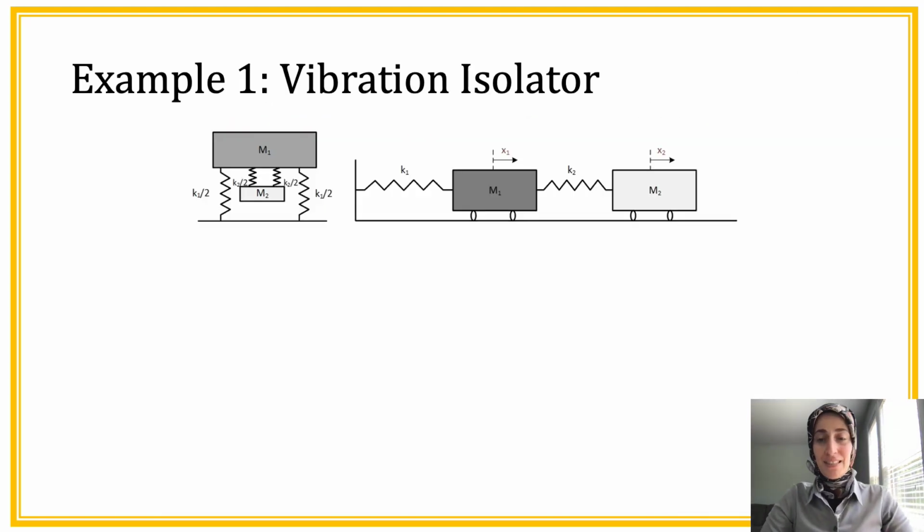When mechanical engineers design a machine or a mechanism, vibrations that are caused either by external forces or due to the clearances in the joints are undesired, and they need to be reduced or eliminated if possible. Vibration control can be achieved by a passive design or by an active controller with the addition of electronics. One cost-effective solution for a vibratory system, which is subjected to some harmonic motion, is the design of a secondary system, which is comprised of a sliding mass and a spring, as shown in the sketch.